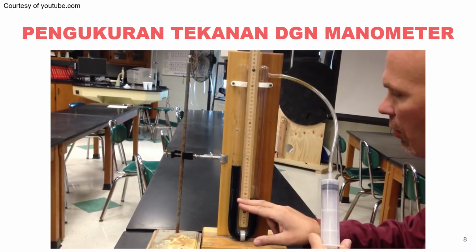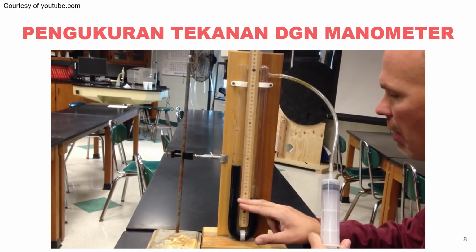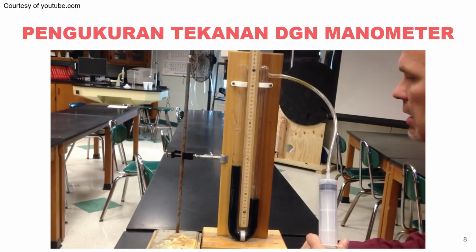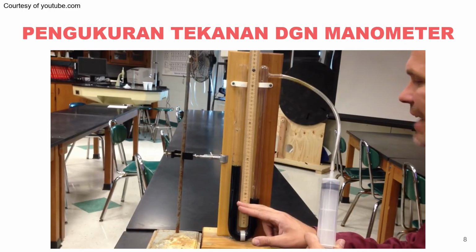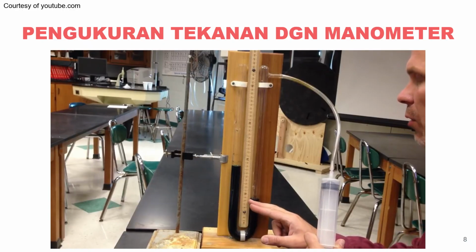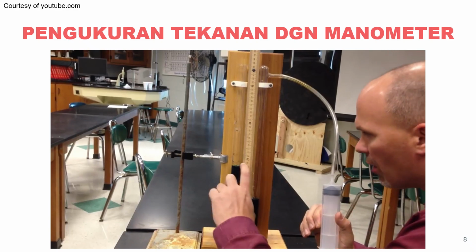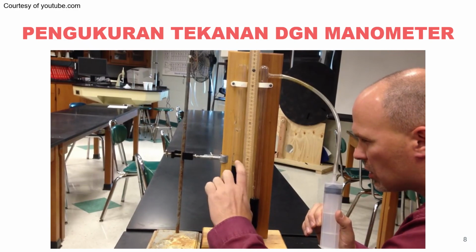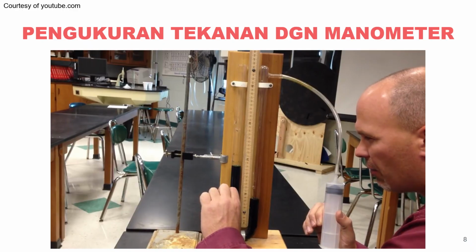Now, if we don't have mercury, we can change that into water. So, I'm sorry, if this is water and not mercury, we can compare it to mercury's density by height times density equals height times density. Because mercury is 13.6 times more dense than water, its height is going to be 13 times smaller. A heavier volume of water, cylinder being supported. Remember, we're supporting a certain weight, and for the same amount of weight of mercury, it's going to be a lot less volume.